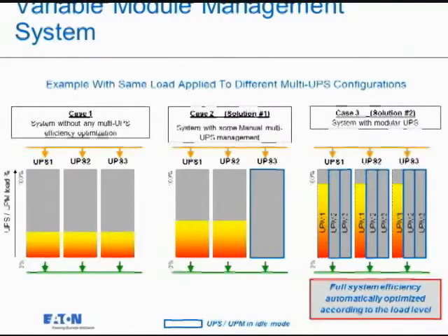So on each one of these 500 kVAs, we had about 100 kilowatts, or about 20% loading on them. And the efficiency went down, because it was more of a traditional style UPS. The battery banks, let's not even go into there from a maintenance perspective on these systems. They were really just grossly oversized.